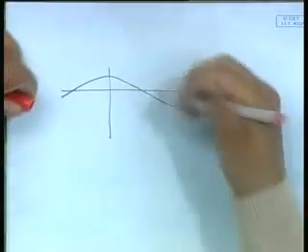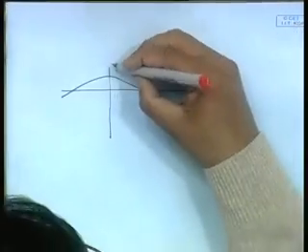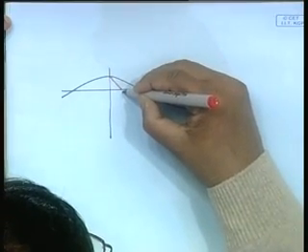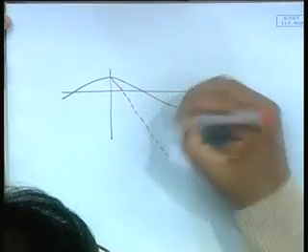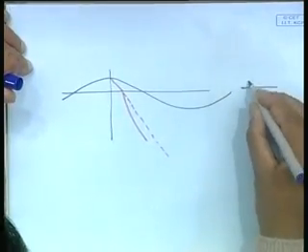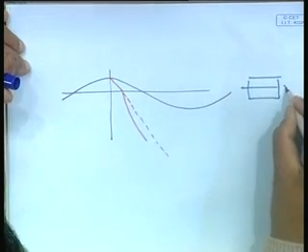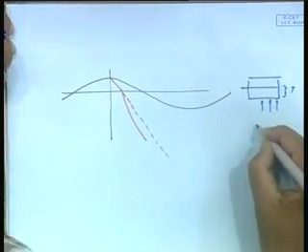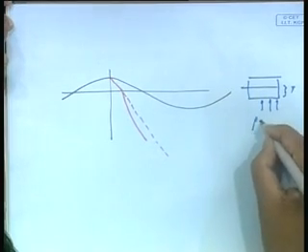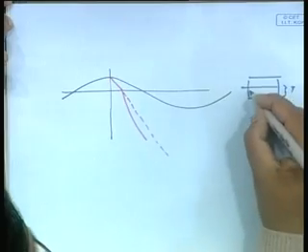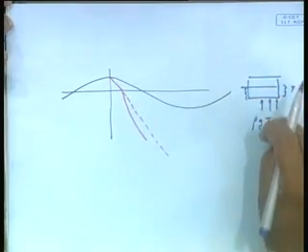Red line. See the pressure, actual pressure under wave under a crest looks like this. This is my straight line, and actual pressure looks like that. That is my actual pressure. Now I have a boat which has a draft of some value. What does it mean? It means that here I had a hydrostatic pressure of rho g into T, which supported my mass. So I must go down that much where my pressure is rho g T.